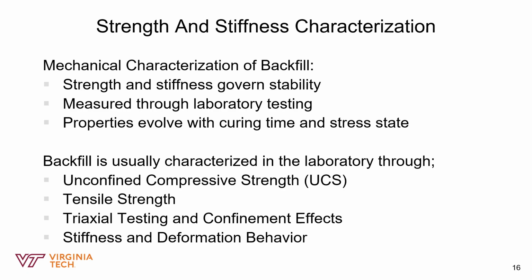like the coring, don't really give intact cores because of the low strength of the backfill material. So if you try to core through the already placed backfill, it usually results in broken pieces, and you cannot take any geotechnical data from that. So usually backfill experts do laboratory tests to characterize the strength. And with the laboratory tests, usually they go with the UCS, tensile strength, triaxial stiffness, and deformation behavior.